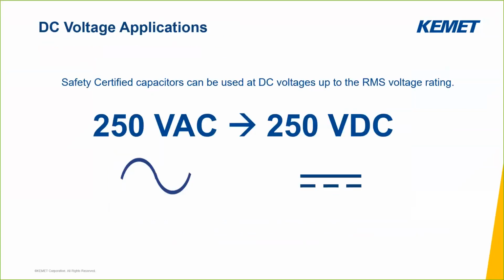Now, certain applications may require interference suppression for DC line voltages and also have a safety certification. The IEC standard allows for the AC rated safety capacitors to be used at DC voltages up to the RMS voltage rating. For example, a Y1 capacitor at 250 volts AC can be used as a Y1 capacitor at 250 volts DC. Some suppliers can rate these to higher voltages, but we have to go through a qualification. But if you purchase a safety capacitor with an AC voltage, you can use it at the RMS rated voltage at DC.